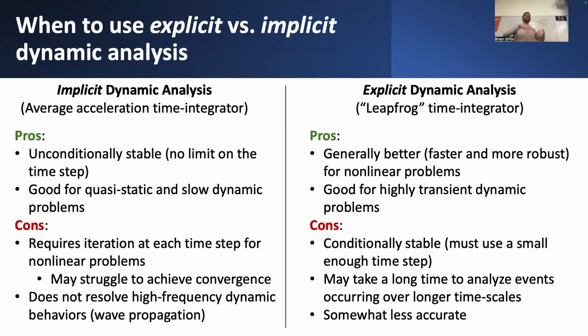If you can include all kinds of nonlinear behavior and it doesn't really increase the overall solution time that significantly, you'll at least get an answer. It's usually pretty good at chugging through some of those situations because it doesn't have to do this nonlinear iteration procedure as you would need to do in an implicit dynamics calculation. But again, it gets prohibitive for explicit dynamics if you have to take a lot of time steps, either because you have a really refined mesh or you're trying to run an analysis that is intended to run for a relatively long duration of time.